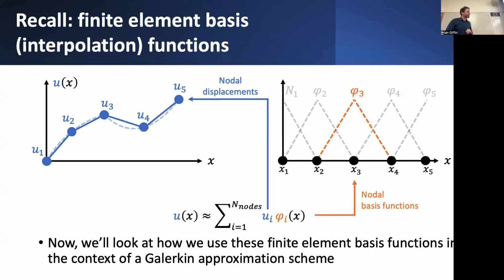So the lecture from Friday talked about a particular choice of basis functions that can be used to express or represent some function as just a finite set of values, which we interpolate using these specialized functions, basis functions, which themselves are nothing more than the so-called finite element basis functions, or these hat-shaped functions, kind of funnily defined.